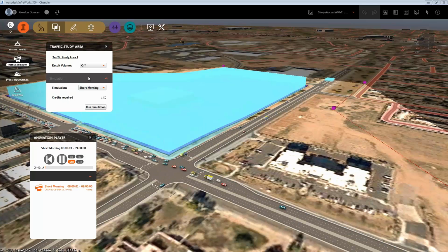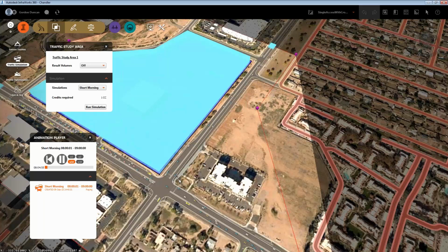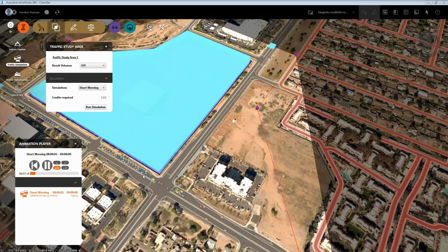Great. Next question is, can you get HCM reports out of the model? Not directly. So HCM is Highway Capacity Manual, and those levels of service that we were talking about, those are calculated internally, and you can see the colors displayed are linked to the Highway Capacity Manual levels of service. As yet, we can't generate reports out of this.